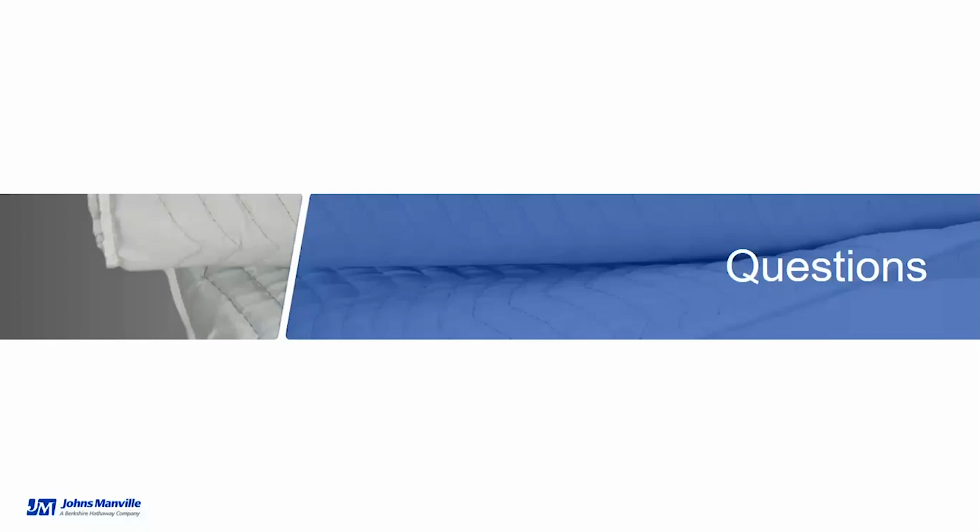The next question I have is for you, Mary Beth, and that is, why did you only use tap water for the first part of the testing and then the chloride solution for the second part of the testing on the NACE TG 516 testing? So that's really just to give multiple conditions to the system so that you can see the different variation in severity between the tap water and then the worst case scenario of the chloride solution in the water.